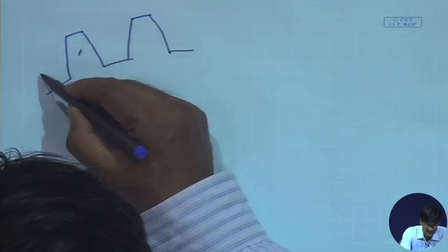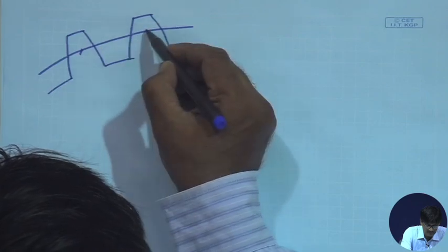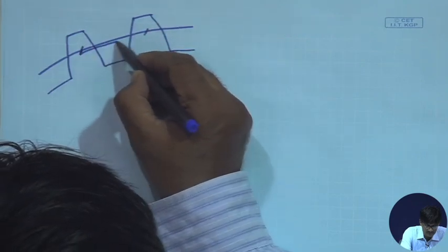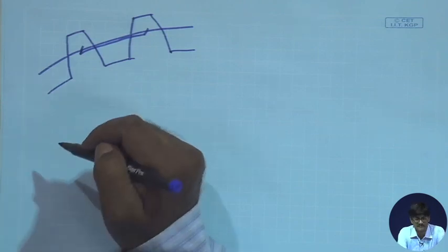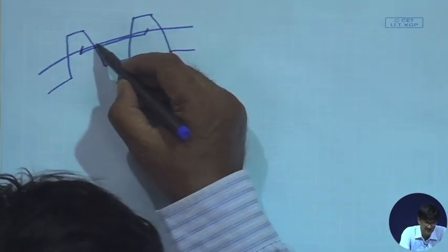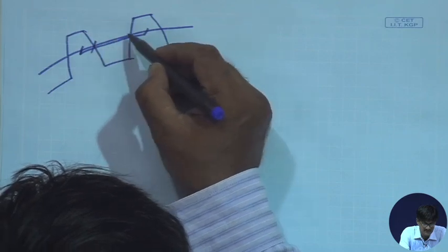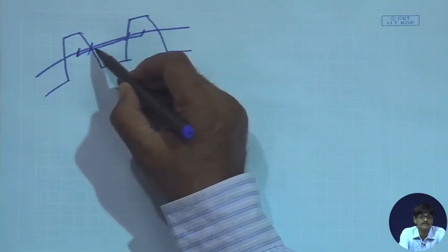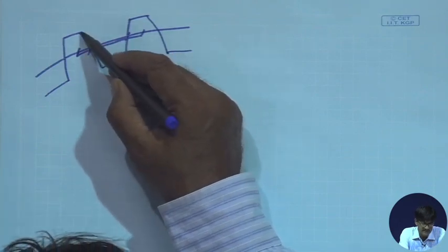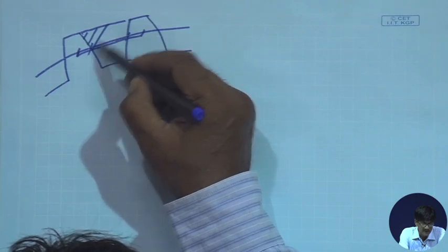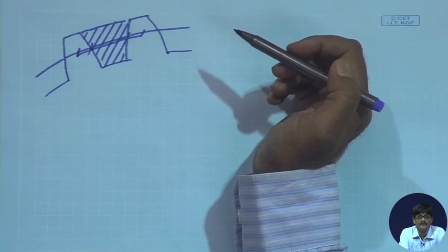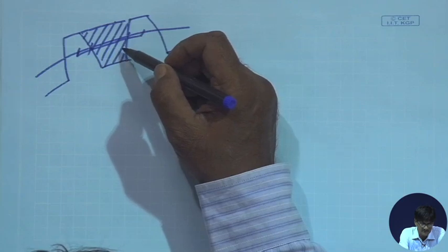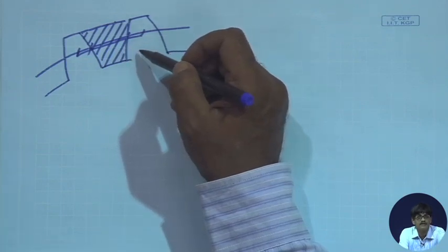This thing is dictated by module. This circumferential distance is dictated by module. In the same way, we can say that in the tooth space, this distance is dictated by module. But if this distance is dictated by module, it does not necessarily mean that this whole shape is dictated by the module. No. What dictates it then?